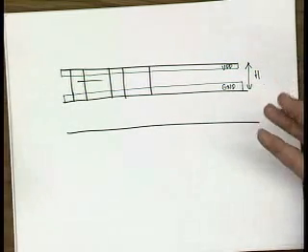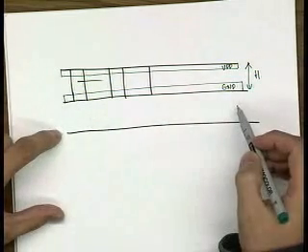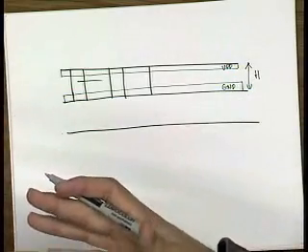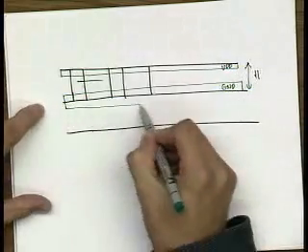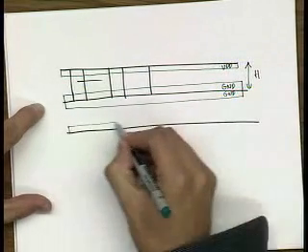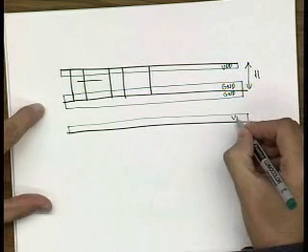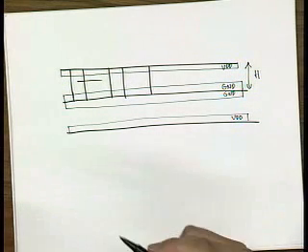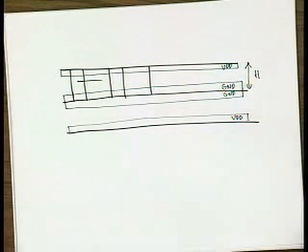Now the next thing you do when you route these rows below is you mirror the cells. You flip them over. So then you have another ground over here, and then you have VDD over here. And this way you can really achieve the high packing density.